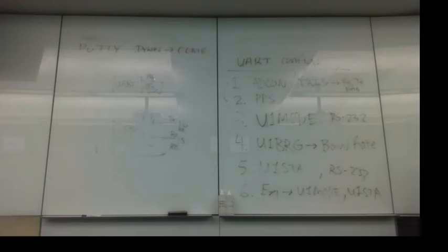If you round to the low integer, then you'll always get a positive error. If you round to the high integer, then you'll get a negative error. So there's 2 different equations. One for BRGH bit equals 0, that's low speed mode. That's in the mode register. And the other one is high speed mode. And the difference is one divides the instruction clock by 16, the other divides it by 4.